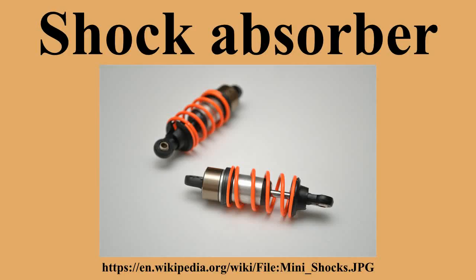These grooves allow the piston to move relatively freely in the middle range of travel and to move with significantly less freedom in response to shifts to more irregular surfaces, when upward and downward movement of the piston starts to occur with greater intensity. This advance allowed car designers to make a shock absorber tailored to specific makes and models of vehicles and to take into account a given vehicle's size and weight, its maneuverability, its horsepower, etc., in creating a correspondingly effective shock.